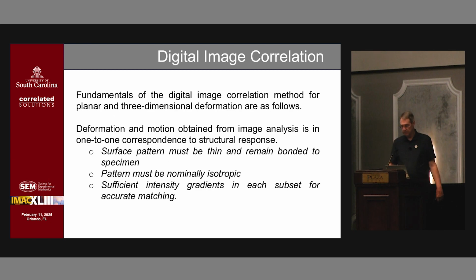So what are the fundamentals for the method? The fundamentals are very simple. They deal with the pattern matching, whether you do stereo DIC or 2D DIC, the fundamental is in the matching of the patterns. So the pattern is where you start. You have to have specific aspects of that pattern to be able to extract visual-based measurements and infer from those the motions of the specimen that the pattern is bonded to or is incorporated within.